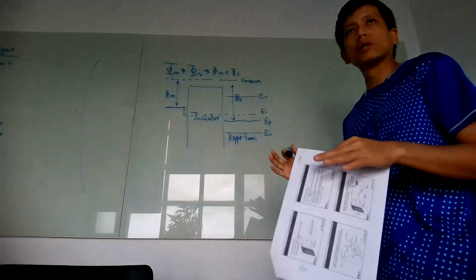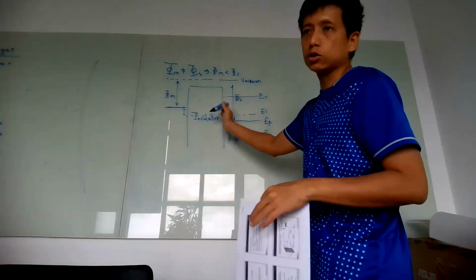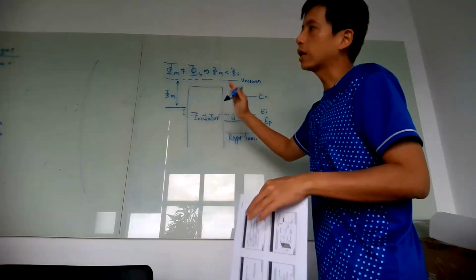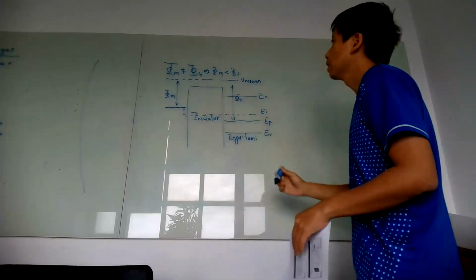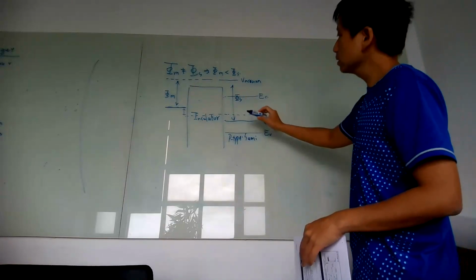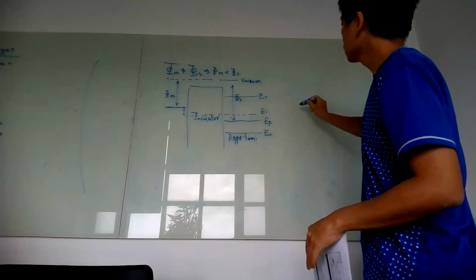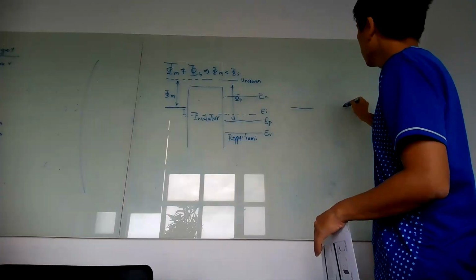A similar thing happens in a metal-insulator-semiconductor connection. What happens here is that even though we do not have the exchange of free electrons and holes, we have accumulations along the surface. Once you have the accumulation of electrons and holes, you get an electric field charge in between the insulator. So that is the way we did it here. The first thing is that we need to align the Fermi level from here to here.